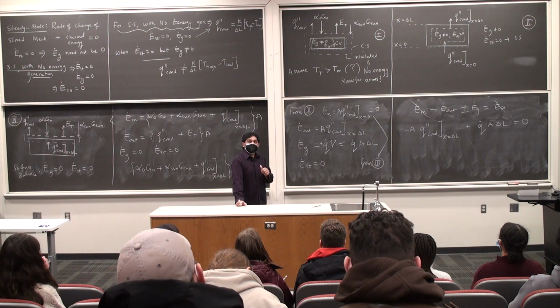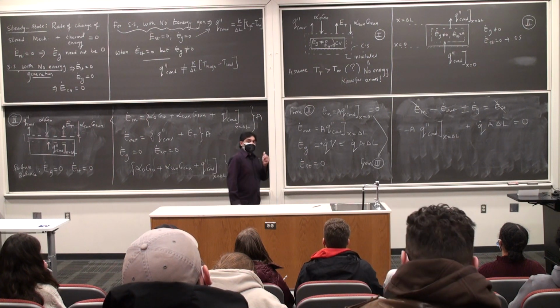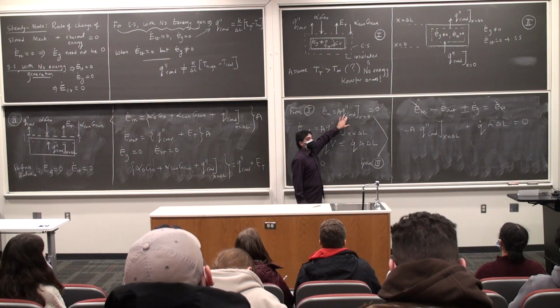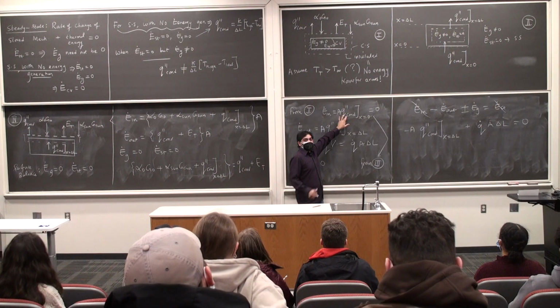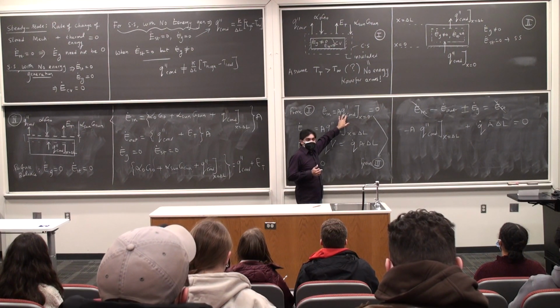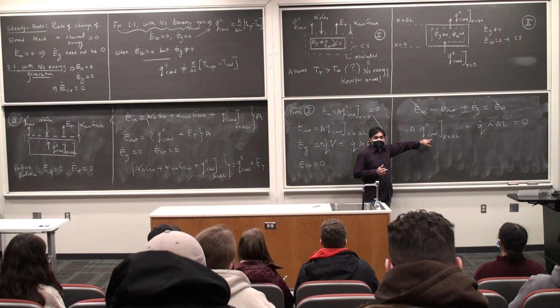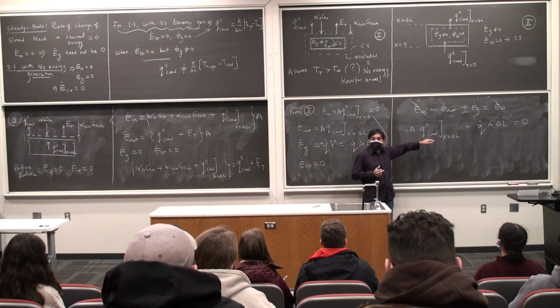That's a very tricky problem indeed. If either of these two or both of them are true, then the conductive heat flux throughout the body is not the same at all points. The flux at the bottom is no longer equal to the flux at the top surface. It's quite obvious to see that's not the case. This is a non-zero value.